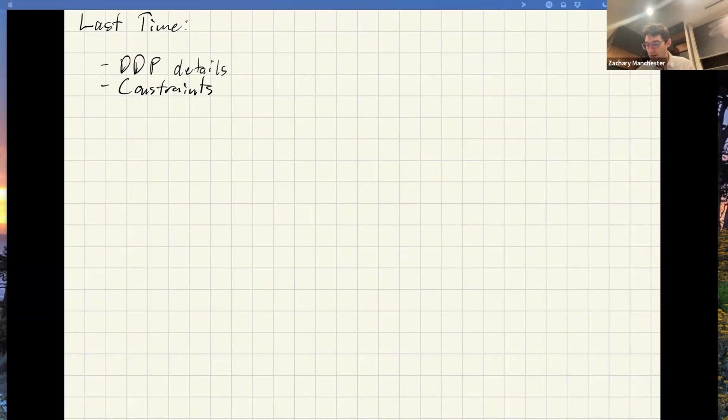Okay, so today we're going to talk about the other major paradigm for nonlinear optimal control, nonlinear trajectory optimization, which are called direct methods, in contrast to indirect, which is the shooting-style, DDP-style methods. These methods basically take the optimal control problem as it is, without any dynamic programming ideas, just discretize time and throw it into a big nonlinear programming solver. That's the big idea. As a result, they're really good at dealing with arbitrary constraints. You can put any kind of constraint you want on there, and the solver will take care of it for you. So that's the big thing for today.